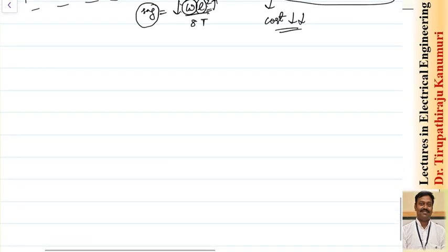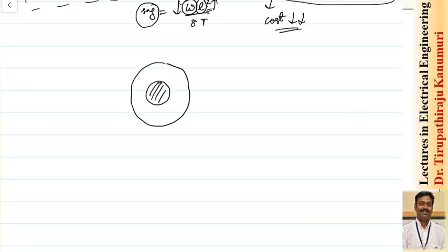Now coming to the underground cables. In underground cables, there is no concept of tower or sag. There will be a conductor, and above this conductor lies the dielectric material. Let us assume the inner radius is small r and the outer radius is capital R. So capital R minus small r will remain constant for a given voltage, because it should withstand the required dielectric strength. Now let us assume the size of the conductor is decreased.